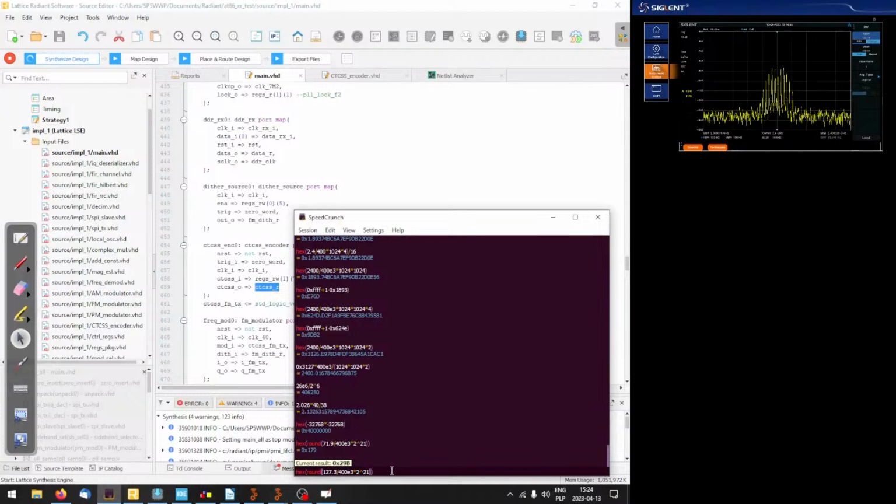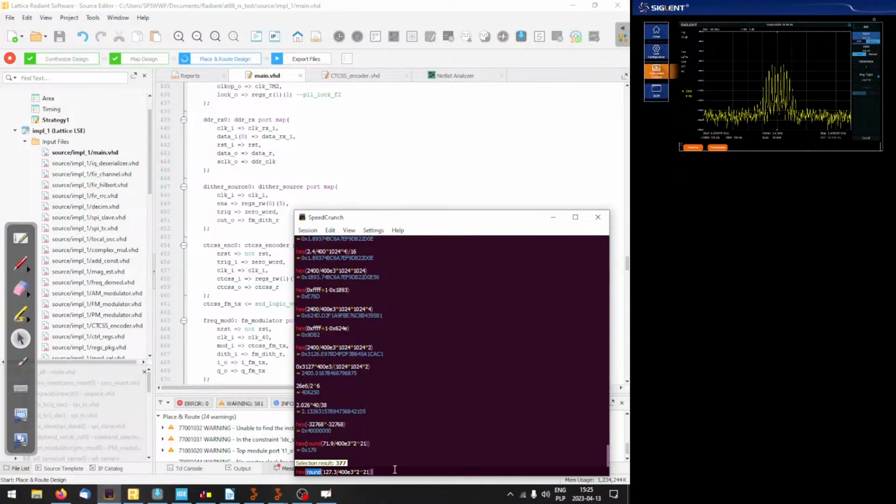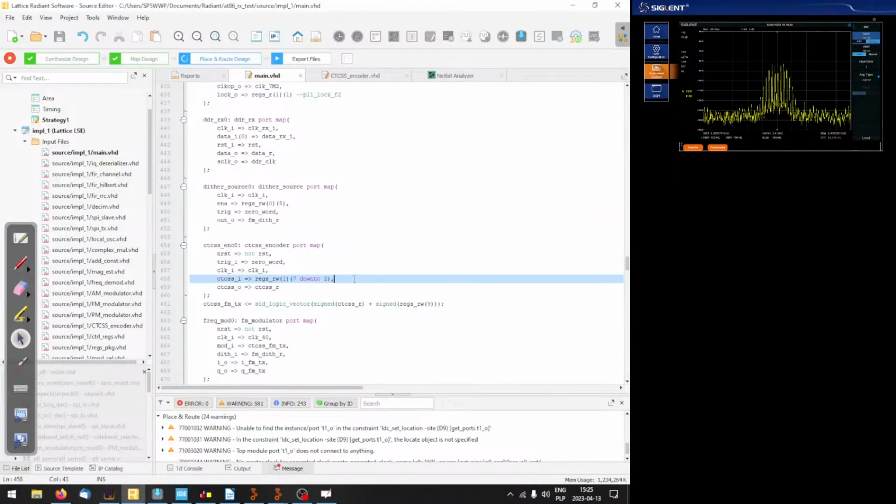So all of that combined gives us the value that we have to add over and over again to the phase accumulator. And then when we take the 10 most significant bits out from that, we should be able to get a sine wave of exactly this frequency, plus or minus some error. Because of course that value is not an integer. We're using rounding here. So that's a rounded value. All right, so looks like it might work.